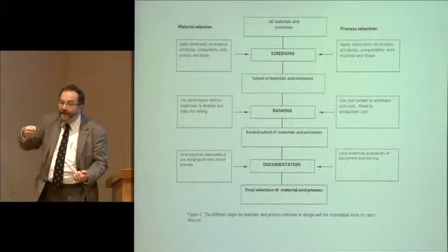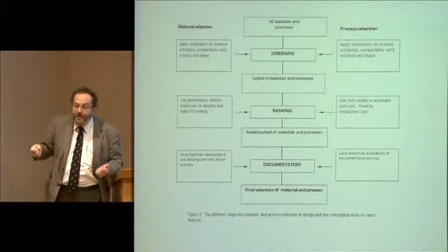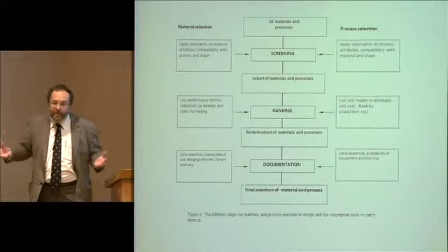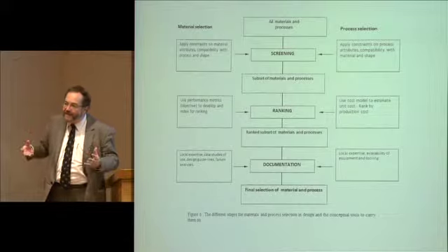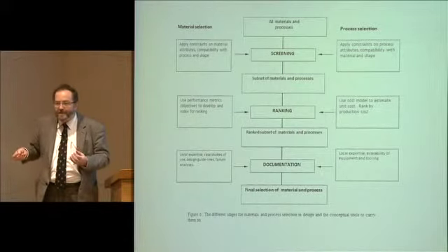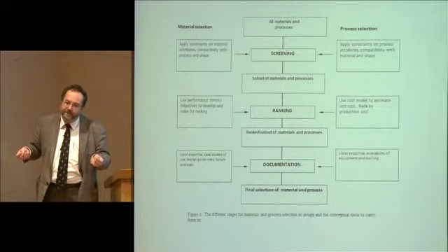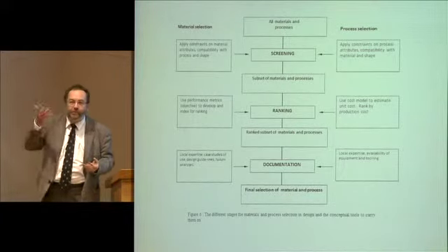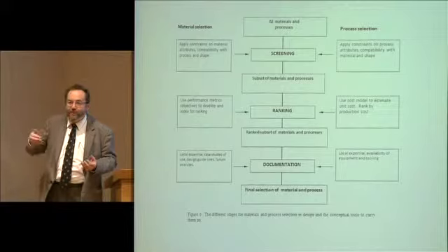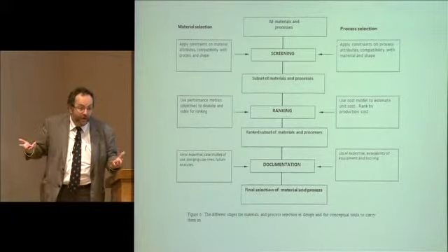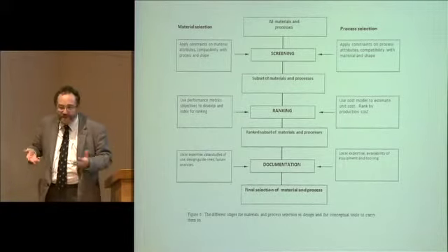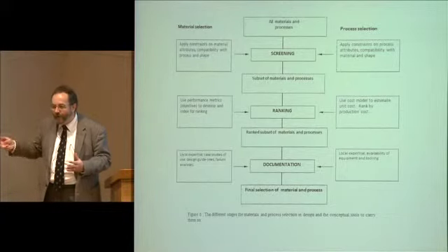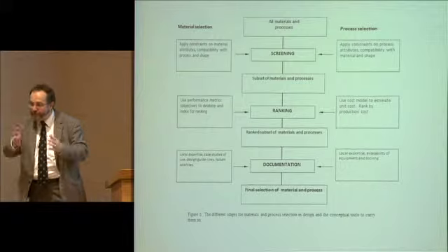So you have a tie rod, something that needs to be very rigid and very lightweight, a type of constraint. Well, the property that characterizes the material's relevance is its Young's modulus divided by its density. It needs a high modulus and a low density to obtain these properties. But things are actually very explicit. It's E divided by ρ. It's very easy.